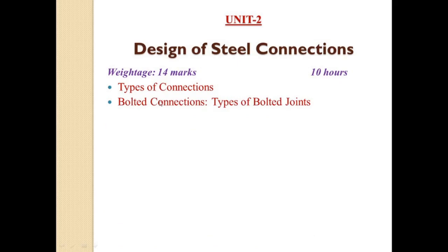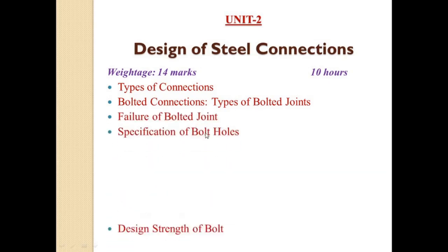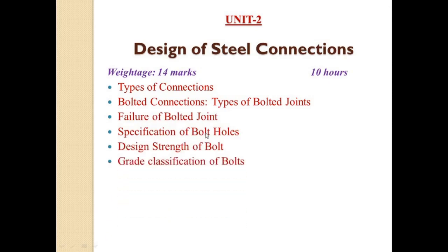Next is bolted connection. We know the types of connection, bolted and welded connection. So from that, part A, we are going to discuss bolted connection. In that, types of bolted joint, then failure of bolted joint, specification of bolt holes, then design strength of bolt, then grade classification of bolt, and lastly analysis and design of axially loaded bolted joints.